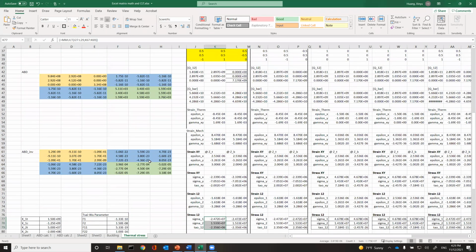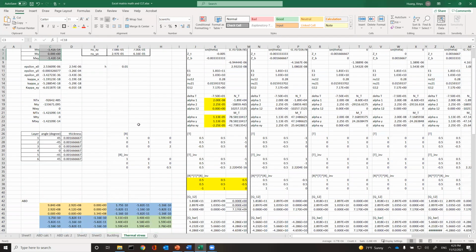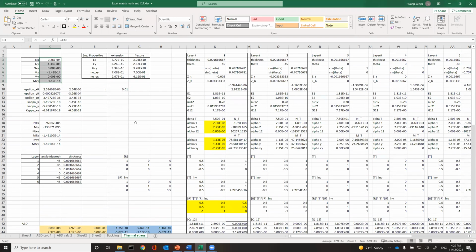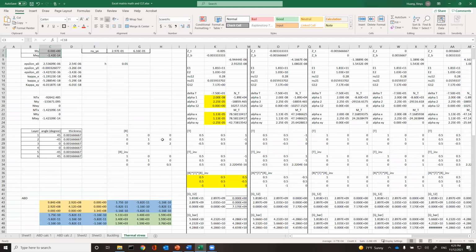And if you have a combined thermal and mechanical load, you would put a combined loading over here. You would calculate another problem with pure mechanical loading. You calculate stress, and then you superimpose them together. So your true stress with both thermal load and mechanical load is the combination of your solution with pure thermal load and pure mechanical load. You put them all together, you sum them up. Okay. All right. Any questions so far?